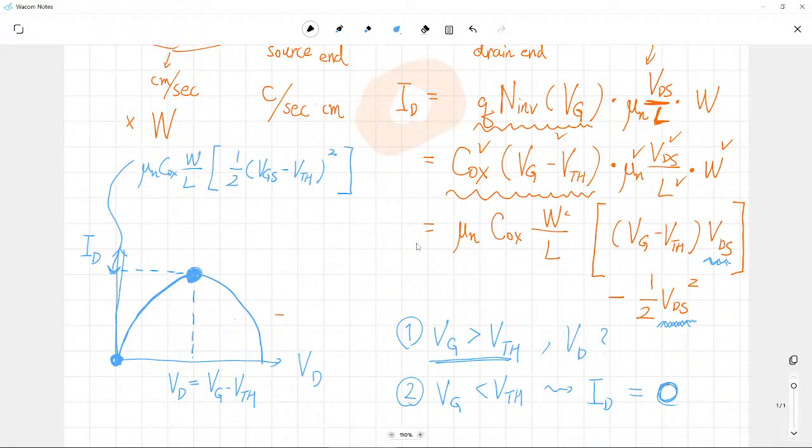I mean that threshold voltage, you do not select the threshold voltage. Threshold voltage is fixed by the fabrication company. However, as a designer, you can select your operation voltage. When you operate your device with a high gate voltage, then you can expect, oh, I can use a lot of current. But if you operate your device with a lower gate voltage, close to threshold voltage, then what will happen? The maximum current you can achieve is relatively small.